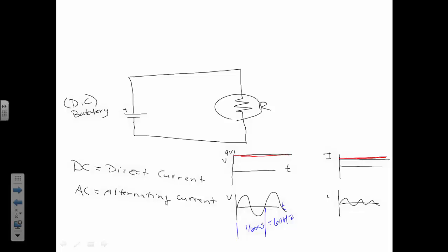And what's our peak voltage on here? If it's 120 volts, 60 hertz, so what's our peak to peak here? Well, what's our amplitude? Nope. It's 157 volts. Obviously, it's 120 times the square root of 2. It turns out this is a root mean square voltage, so I won't get that wrong. But that's another story. I got you on that one, didn't I? We'll get to that at 6 o'clock.